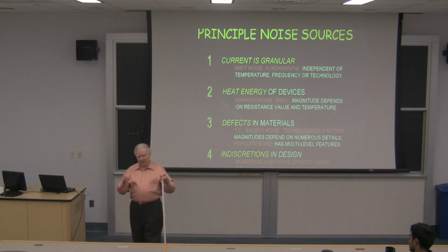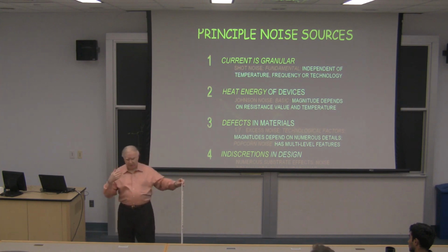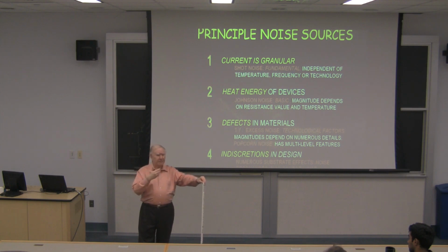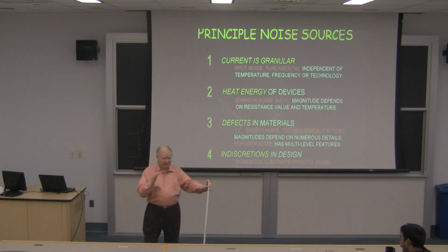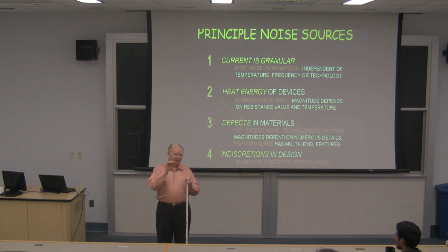Here's another example of how you can gain insights without accuracy. I introduced a parameter, a pretty obvious one, that modulates the parameter BF, which is in a bipolar model, the factor that most determines the DC beta. And I can sweep that from, well, I routinely sweep 1/3 nominal to, say, 1,000 times normal. And you may say that's ridiculous, beta doesn't vary that much. And I say I don't care. Because what I'm looking at is some parameter, let's say it's a voltage reference, getting away from noise a little bit. And I look at the output of this reference, and I sweep beta F from 1/3 nominal to 1,000 times nominal. Nothing should vary.